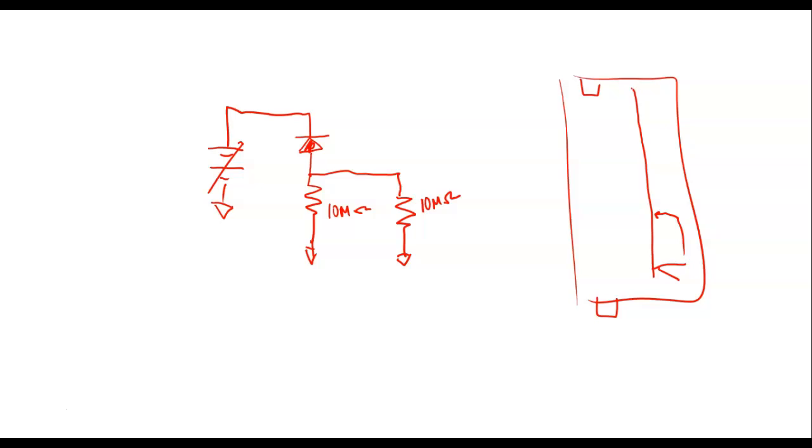So that's something you got to think about, that voltmeter. You're not putting an infinite resistance in parallel with something. You're putting about 10 megohms in parallel with something. Now, if you're reading across, like we're reading across a 1K ohm resistor, and you're putting 10 megohms across, that means nothing. And we call it the 10-to-1 ratio. So what that means, if what you're putting in parallel has 10 times more resistance than what you're trying to measure, we just ignore it. It's not going to cause any problems.